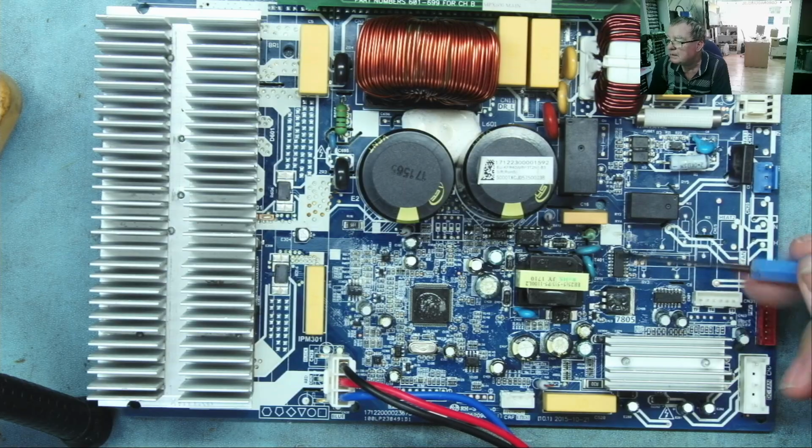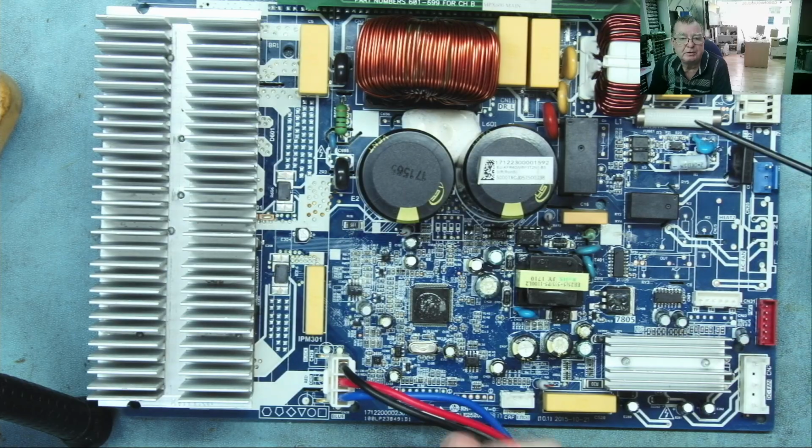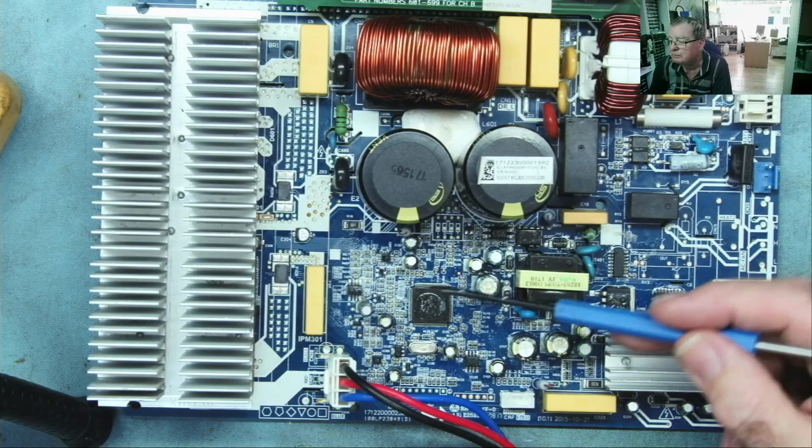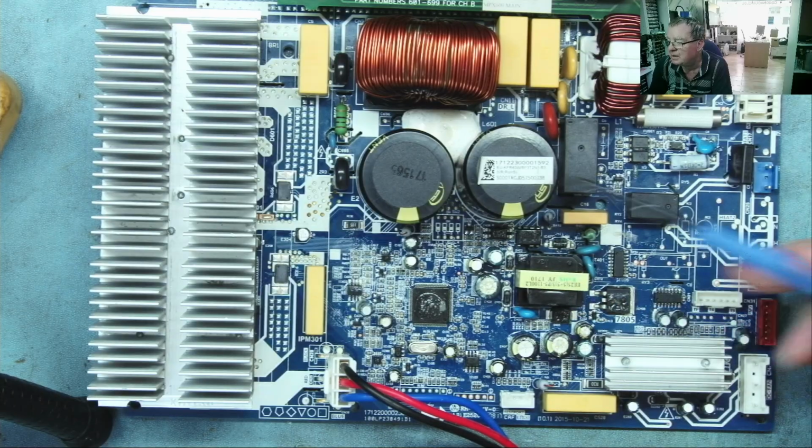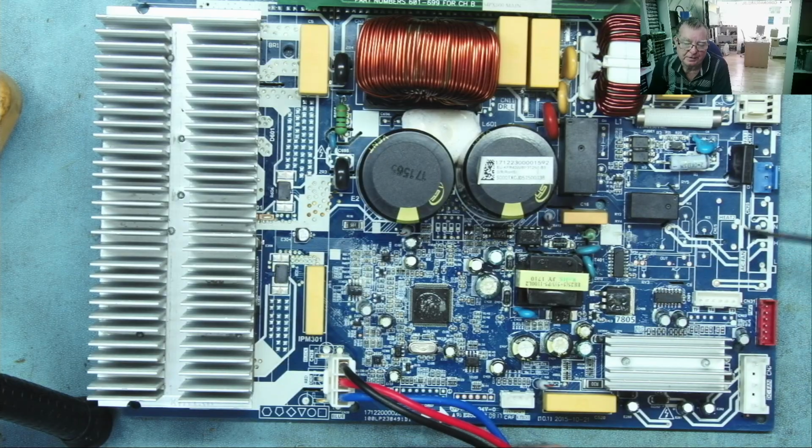Now, you'll often find on the motherboard, obviously, a processor, on here a microcontroller. So this is a microcontroller, and this is talking to the outside world. It's receiving inputs from various sensors, for example, like a thermocouple or a humidity sensor, speed detection from a motor, whatever. Yeah, it's sensing the various peripherals attached to the board. And it's also driving things like switching on or off a fan or something like that, okay? Displaying onto a 7-segment display some sort of operational code or error code.